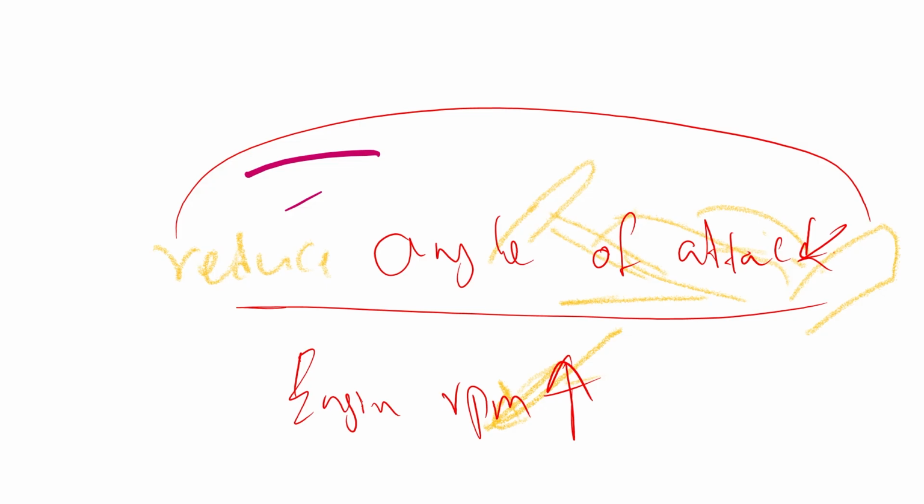And next, let's talk a bit more about the factors that affect the performance, right? There can be a lot of factors that affect the performance of an aircraft, especially these drones. If you have ever flown an RC aircraft, you might know that the CG, or the center of gravity, plays a very important role, right? So this is the wing, and we have the front propeller, and we have this rudder, and we have the stabilizer. So CG is somewhere here.